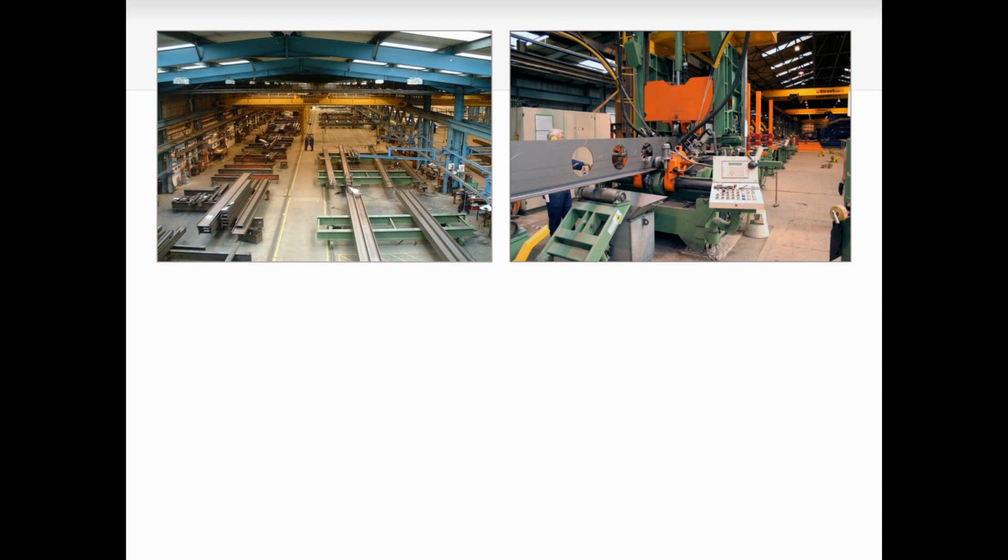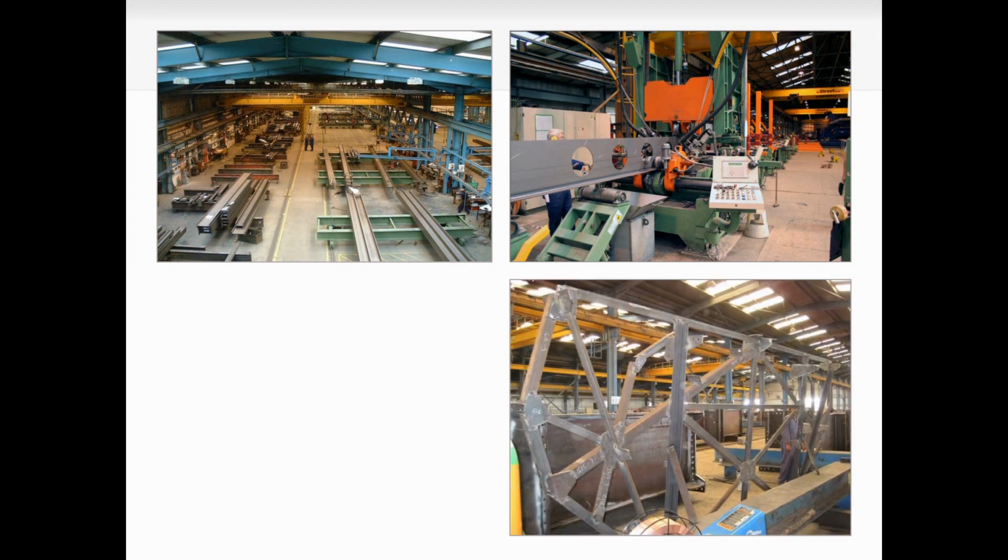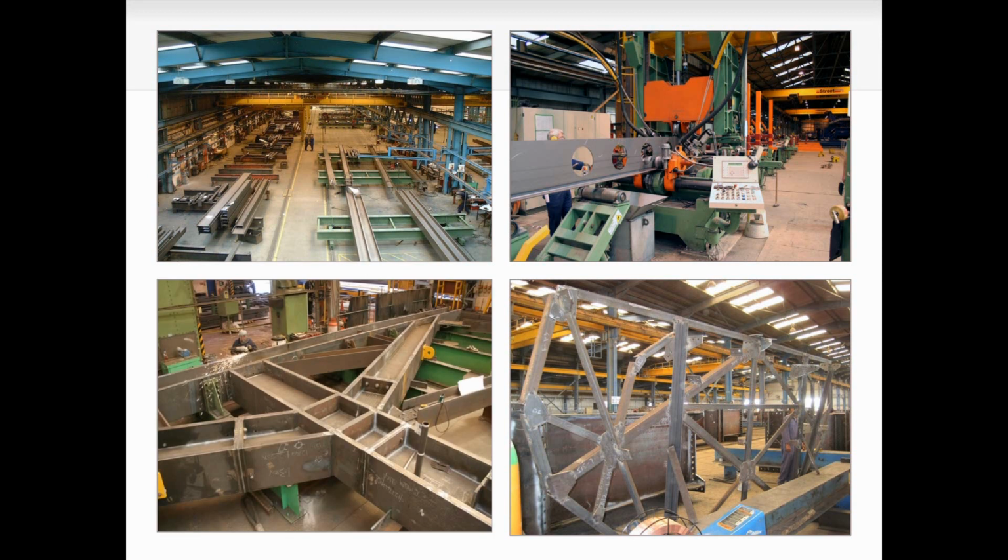Why is that? Well, most fabrication shops are set up for throughput, where standard sections undergo standard processes as they pass through the shop. Whilst complexity sometimes can't be avoided due to project geometry, it's more economic to avoid details with lots of stiffeners in favour of slightly heavier sections. As we've just seen, the effect of fabrication costs is far more significant than that of nominal additional material. So unless complexity is driven by external factors, it should be avoided wherever possible.